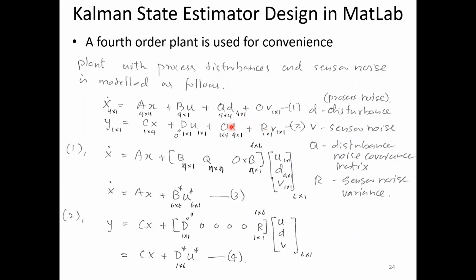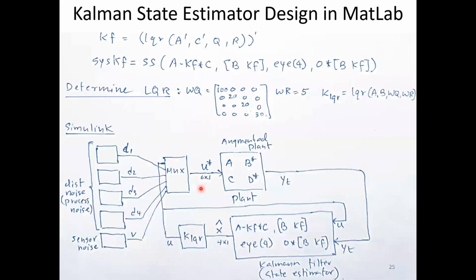So this U is just one of the elements. There are other elements also, right? This is the disturbances. This is the sensor noise. They're also coming in, combining with U to produce U star. So this combination is happening over here. You have the disturbances D and V. All of the sensor noise and random process noise are here.